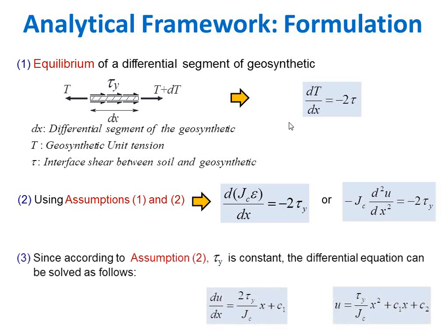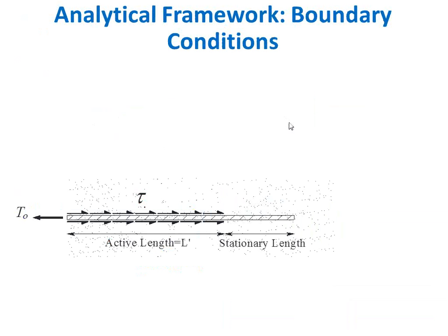But we're not done, because once we have a differential equation, we still have not solved the problem. We need boundary conditions. And what I'm going to show you, even though it needs to be this way, we have not seen it in the literature yet. Because for boundary conditions, typically the assumptions that you will see in a problem like this, you have a boundary condition here, a given force, and you have a boundary condition here that is, let's say, zero displacement or zero strain. That's what is typically done, and you end up with equations that do not look good, and the validity of the equations has been questioned when compared to experimental data.